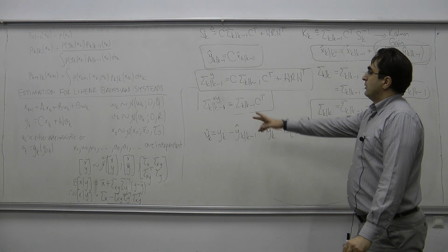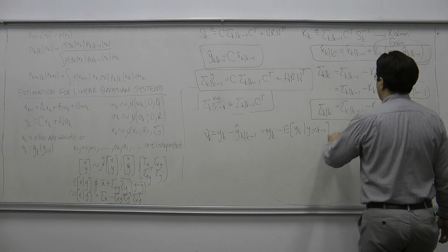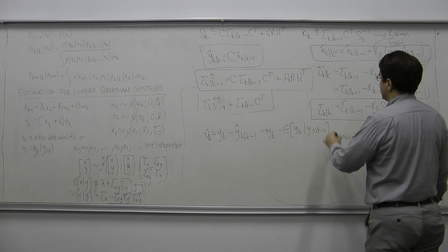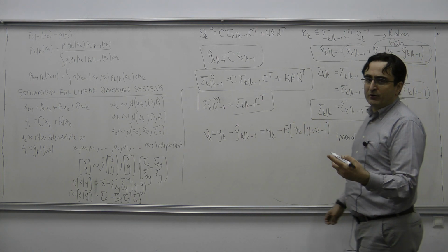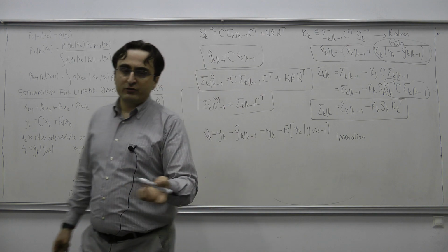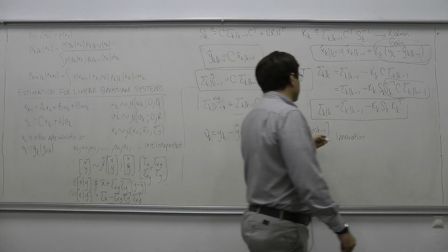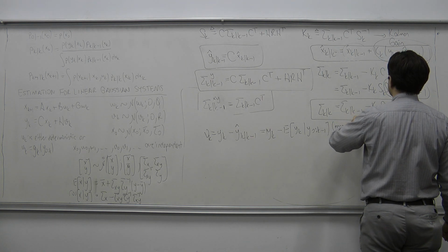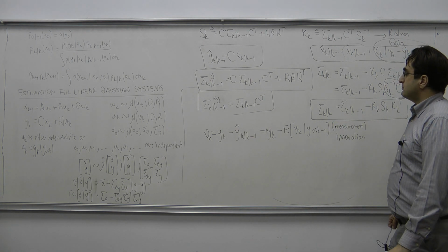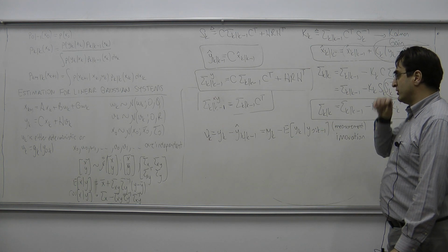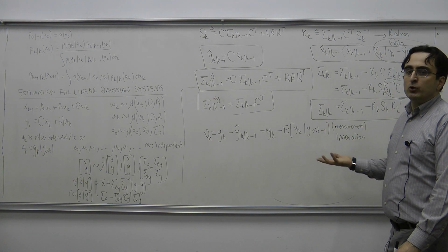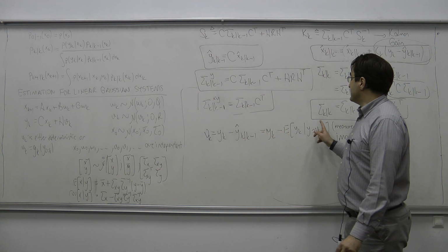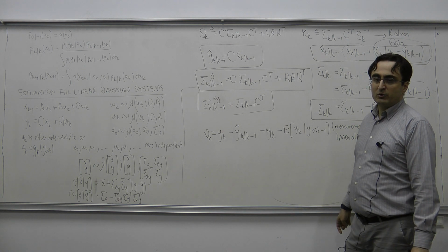We call this the innovation at time k, but sometimes, to separate it from the state innovation that we have seen in the past, it is called the measurement innovation. This measurement innovation represents the new part, the novel part in the measurement y k that is not contained in the previous measurements.